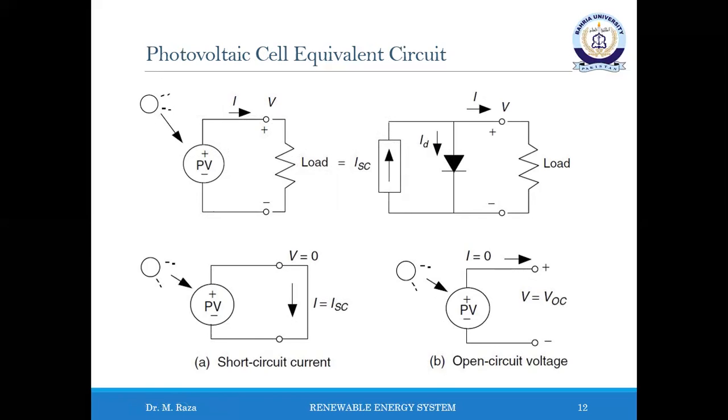When the leads of the equivalent circuit for the PV cell are shorted together, no current flows in the real diode, since Vd is 0, so all the current from the ideal source flows through the shorted lead. Since that short circuit current must equal ISC, the magnitude of the ideal current source itself must be equal to ISC, the short circuit current.